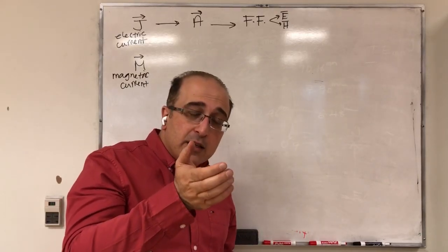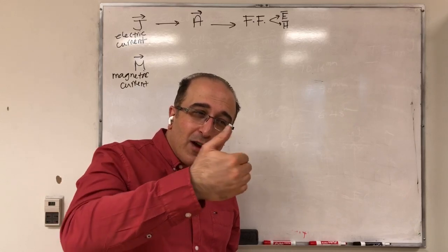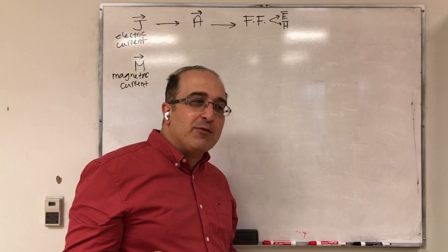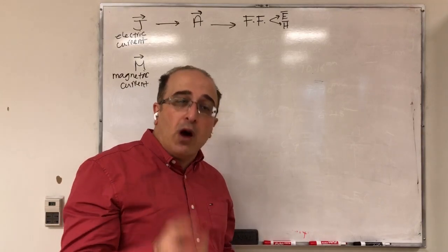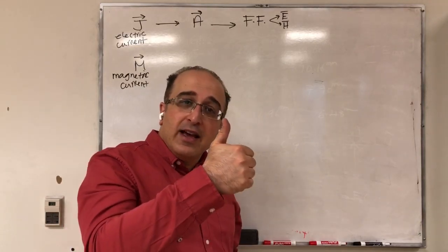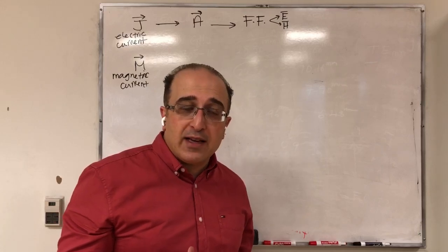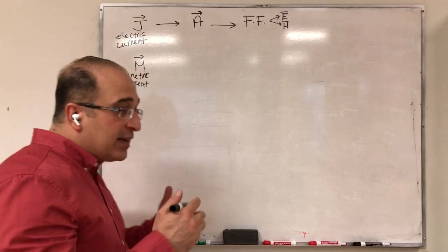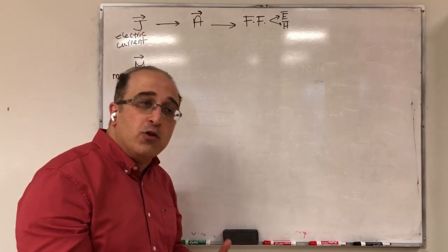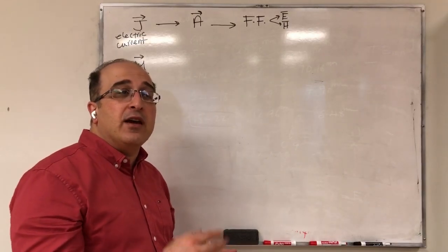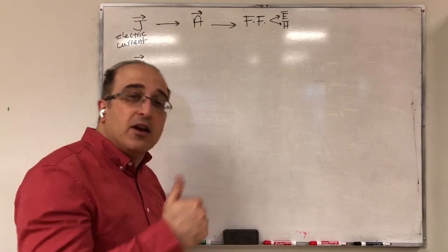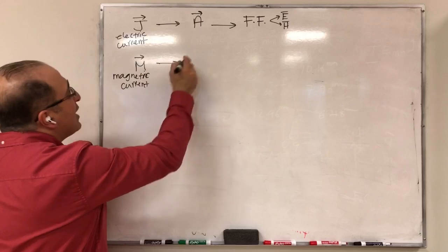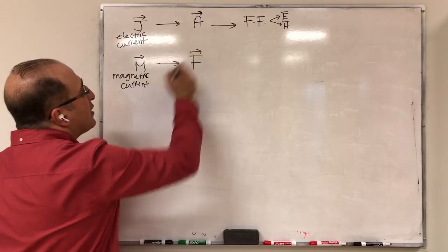But then we said, instead of considering the electric current going in the phi hat direction, because it could create some complication for us in the calculation, we could model it by a magnetic current normal to the loop antenna. We essentially had an electric current on the loop, but we modeled it by a magnetic current perpendicular to the loop. And then we said, if you have that, you can go to electric vector potential.